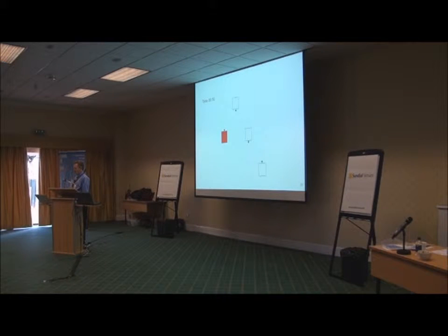Okay, so this is my model of a round trip time, a perfect lift system. You see the red car, it's completely beautifully synchronised. Is this what real lifts do? No bunching at all, absolutely perfect. And so the round trip time with the red car was 120 seconds. And as there were 4 cars, one was leaving every 30 seconds. Because of that, the interval is 30 seconds. So it's 30 seconds between cars leaving, and I'll just run that to prove it. Look, at time 0, a car left, and then this second car left at 30, then a minute, 90, and so on. So the interval is 30 seconds.